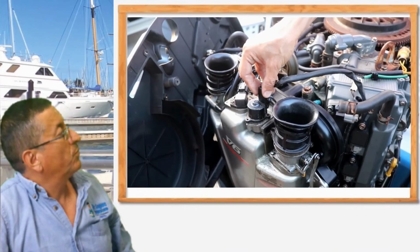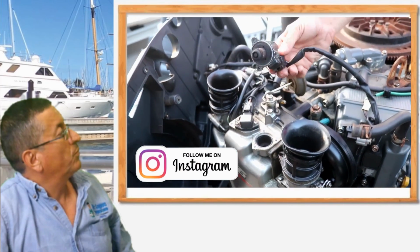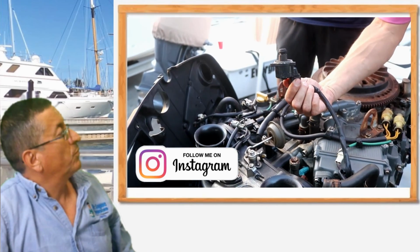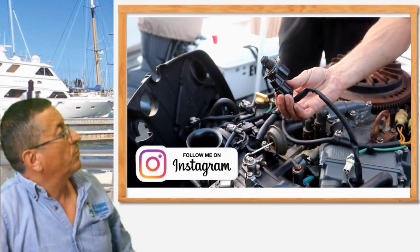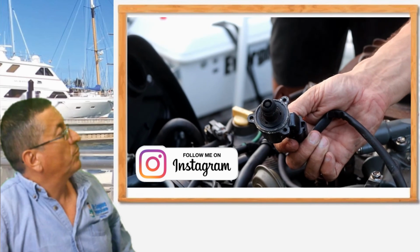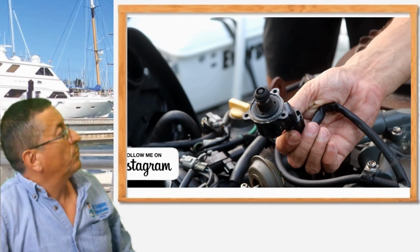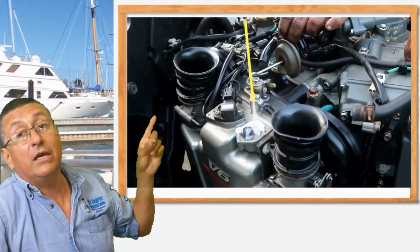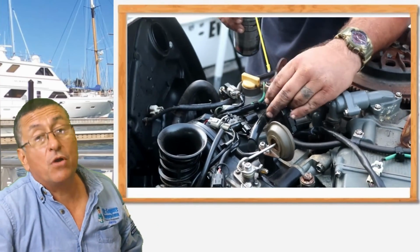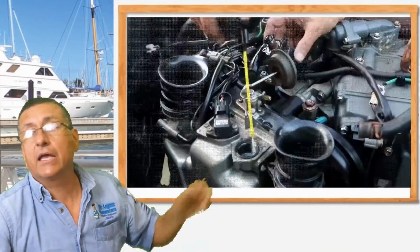Alright. Okay, we are going to remove the IAC in order to verify the condition. Oh, Danny, look at this. Alright, yeah. What is the solution? Well, what we're going to do now is Robert is going to get some Power Tune, and we're going to spray Power Tune and clean it, and then we're going to retest it. Yes, we identified one problem in a Suzuki 250 outboard with the IAC.